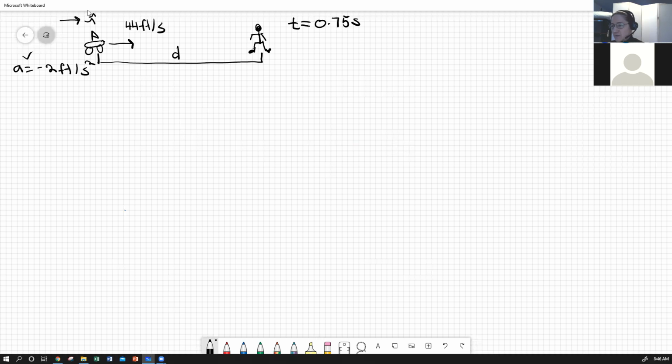And that's used to basically set maximum speeds versus slopes versus hill profiles. So radius of curvature of the hill will determine sight lines, the average distance a person can see. Those are all things that we'll start to tackle with tangent-normal systems and maybe a function for what your line of sight is.